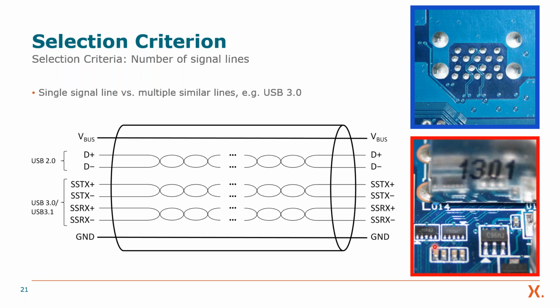And on the other side, you see the ESD protection devices, which are protecting multiple lines at once. This has some benefits. One is that you can actually match the parasitic capacitances, for example, but also the inductances and other parasitics and the electrical behavior of the devices internally. So you can guarantee that there is no big deviation from one pin to another.